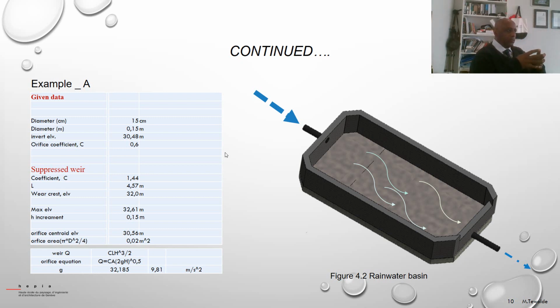And then we need to know, for example, if we are going to construct a basin in concrete or something like that, we need to know all the size and so on, so that we can calculate the outflow of the incoming water just simply using an orifice or weir formula, and that is it.